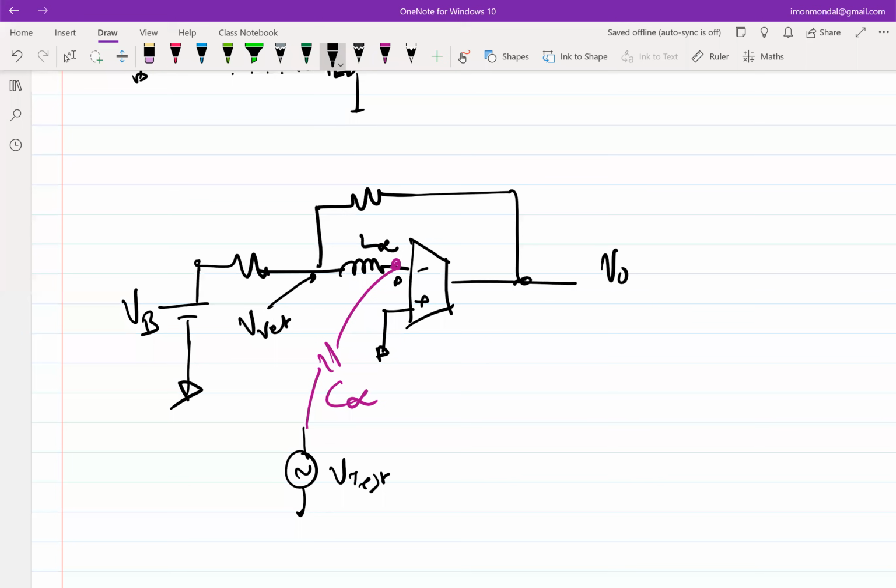You tell me, how will you figure out? Yeah, exactly, right. You have to figure out the impedance and then see, in the operating frequency ranges, this L infinity and C infinity are not getting shorted essentially.